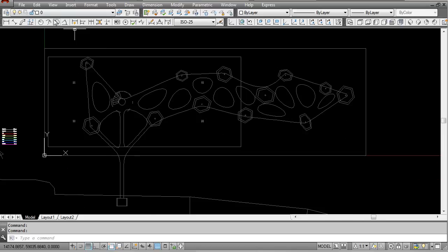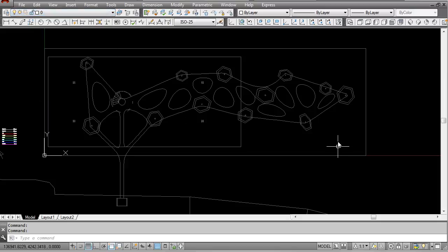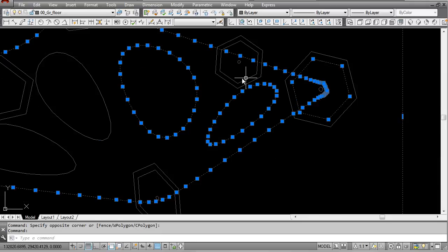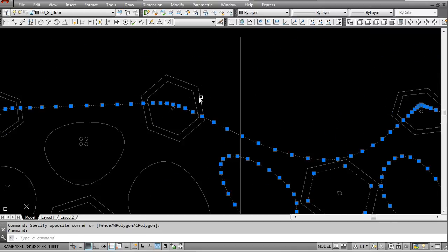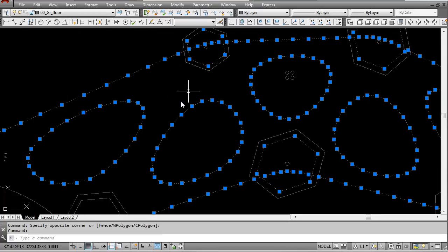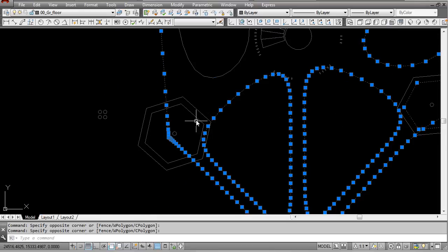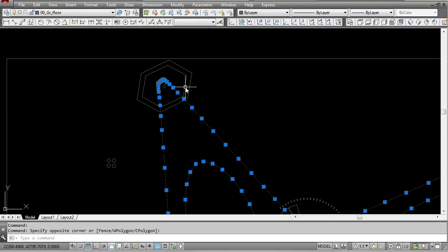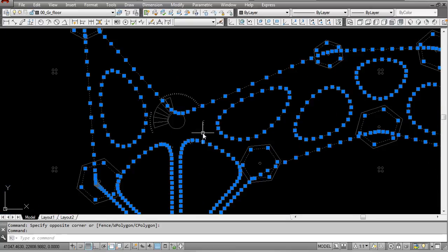So first of all, let's hide all of the layers that we're going to be adding the objects to, and you'll see why in just a moment. I'm going to first select all of the floors. I'm manually going to select all of the lines or polylines that are going to be on that floor layer. It's a good thing to note at this point that if you have a very complicated plan or many shapes to select, it is a better idea to choose that layer within 3D Max before you create the shape. Once you have a new layer created and you create the shape, that shape in 3D Max will be assigned to that layer that you've created and selected.